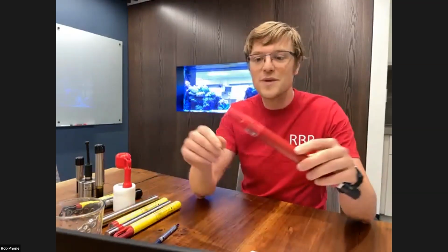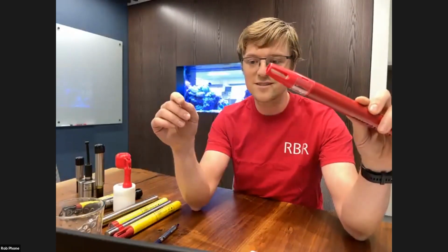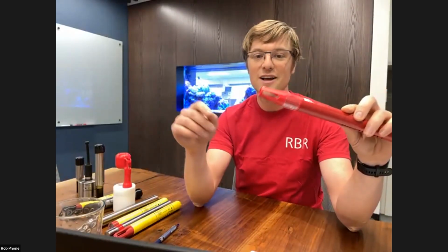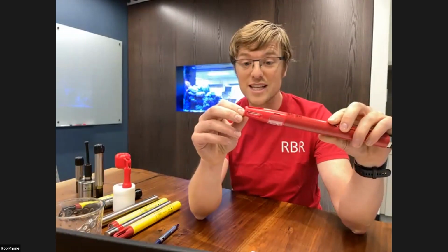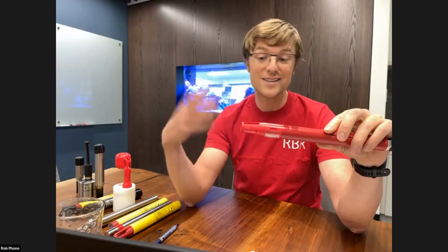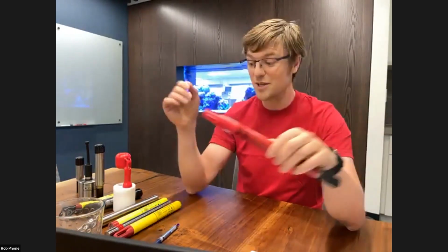So I have a few of them here. You can see this is one of our fast ones, where you can barely see the thermistor there. It's a very thin thermistor made out of stainless steel. This responds very quickly to any changes in temperature and is ideal for any profiling application.